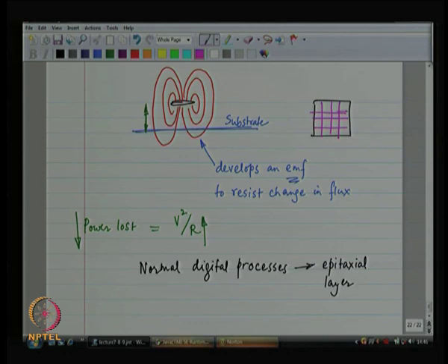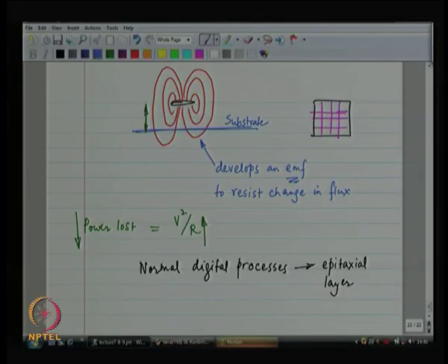Okay. Now, each of these isolated portions are conducting themselves, but because of the trenches the whole thing is not conducting. Now, this reduces the length, I am sorry, this reduces the area over which the EMF is going to develop. So, now instead of a current going over the entire area of the substrate, you have got small currents over small portions of the area. So, you still get eddy currents, but the quantum of eddy currents is reduced significantly.